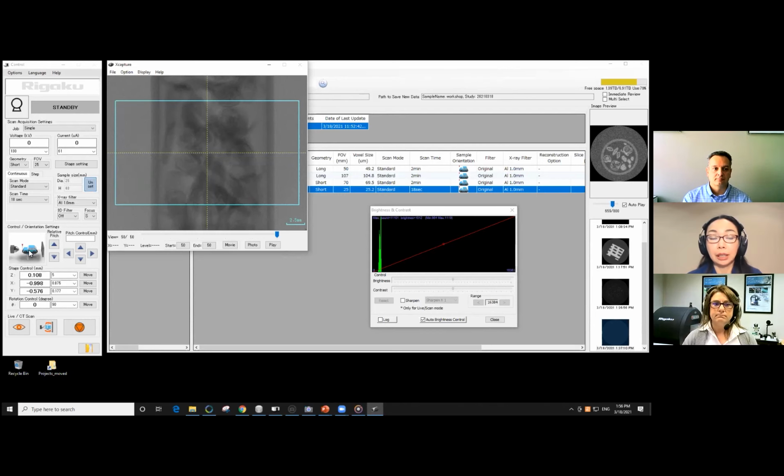Even if you do a scan in 18 seconds and do reconstruction in, let's say, 10 seconds, that's 20, 30 seconds per sample. And you have to remember that you end up obtaining a gigabyte-size file per sample. It becomes a question of where you are going to save all those images, and analysis takes longer to decide whether a certain part passed or failed.